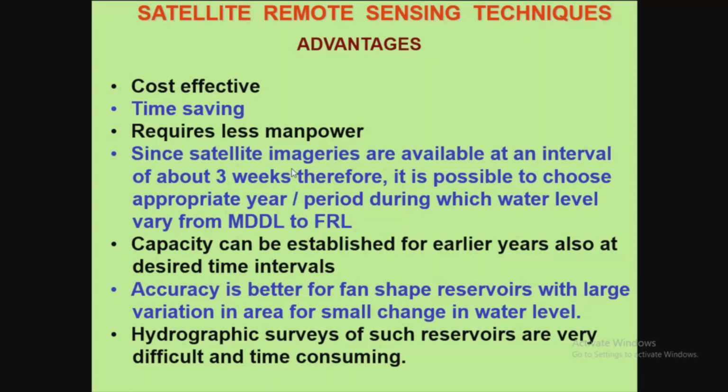Now, accuracy is better in a fan shaped reservoir, but for a gourd shaped reservoir the accuracy is a little less, because for each depth of the reservoir there is a very small reduction in area. That's why. In a fan shaped reservoir, for a small depth reduction, there is a huge reduction in the water spread area. So there are some benefits and some disbenefits also.